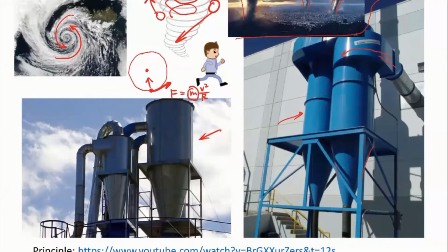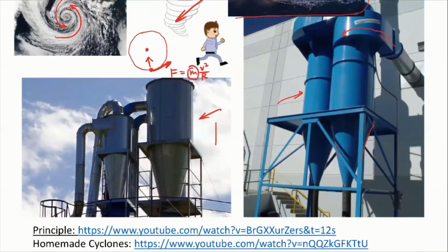So what happens is the air is going to rotate, right? So the heavier particles or the larger particles, because they don't have enough force to support the rotational movement, will just get spun onto the wall. On the wall, you will collect larger particles, and then because of gravity, they will just fall down along the wall, and then finally get collected at the bottom, right?